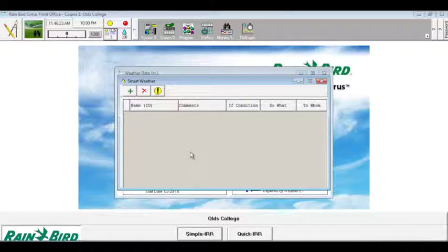We want an alarm that will pause our number 5 greens when winds exceed 10 miles an hour and resume when the winds diminish below that. Shut down the entire system for rainfall greater than half an inch, and pause the irrigation system when the rainfall intensity is above 3 inches per hour.